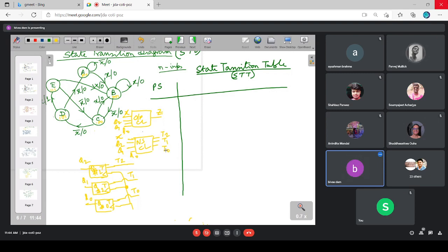So what the new output will be, that I am creating at the present time instant itself. So the D outputs coming from the output of the next state combination logic block are nothing but directly equal to the next required Q values. So in that case, I may say the next state combination logic output is nothing but the next state.